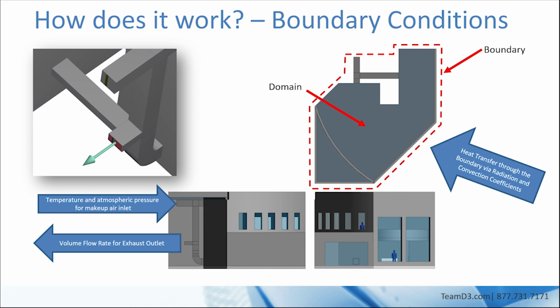Boundary conditions are another essential piece of input for a CFD analysis. Once we've decided what geometry to include in the analysis, we've decided on what's called a domain. The domain is just the chunk of reality that we're simulating. Let's take this lobby, for example. We've chosen the external walls, some internal walls, a mezzanine, and some of the contents as our input geometry. This is our domain. At the external walls, we find the boundaries of our domain. Beyond the boundaries, we are not modeling physics, but assuming what is occurring. It's on these boundaries that we place our boundary conditions.